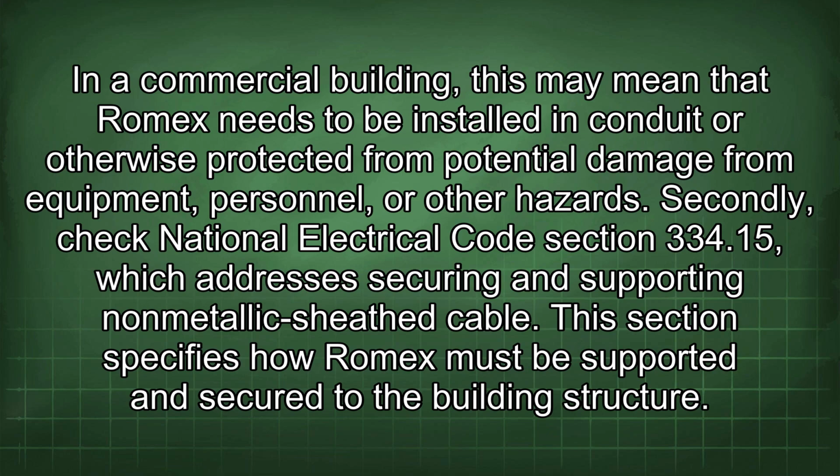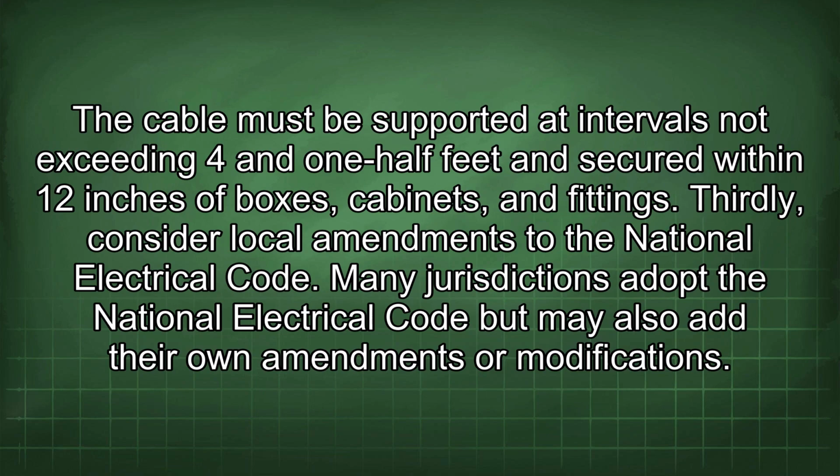Secondly, check National Electrical Code Section 334.15, which addresses securing and supporting non-metallic sheath cable. This section specifies how Romex must be supported and secured to the building structure. The cable must be supported at intervals not exceeding 4 1/2 feet and secured within 12 inches of boxes, cabinets, and fittings.